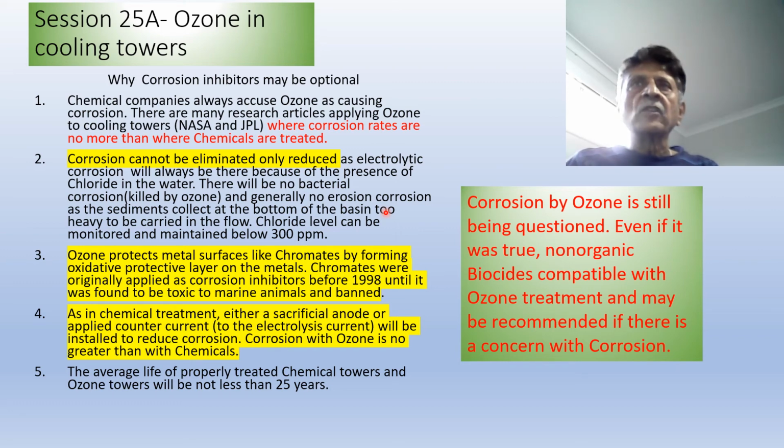So in order to stop or reduce the electrolytic corrosion, we have to ensure that the chloride levels must be monitored and maintained below 300 ppm.